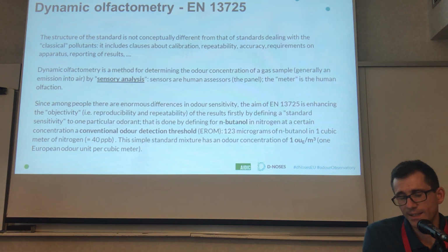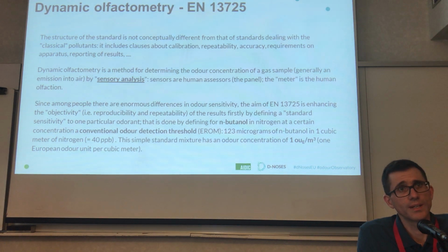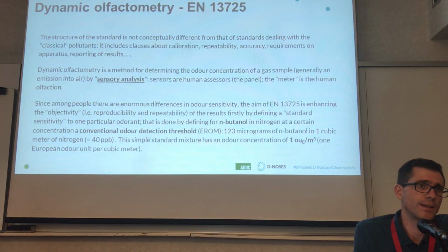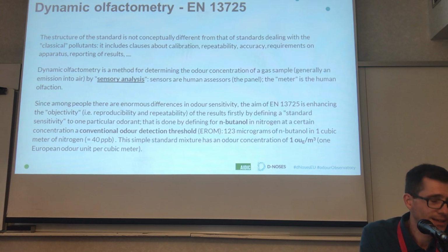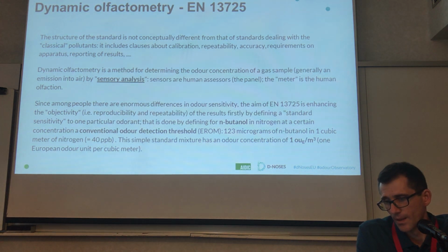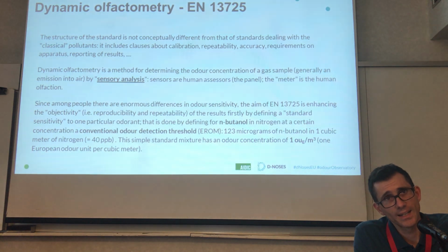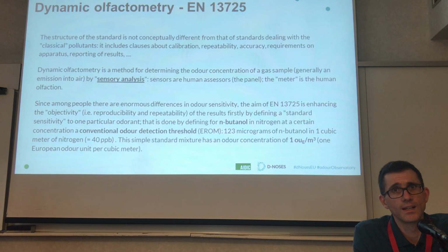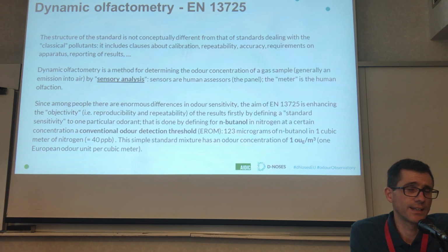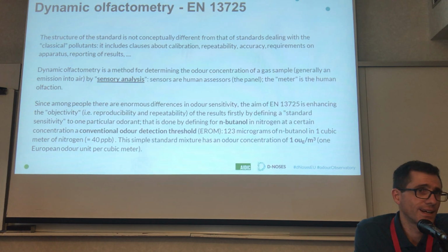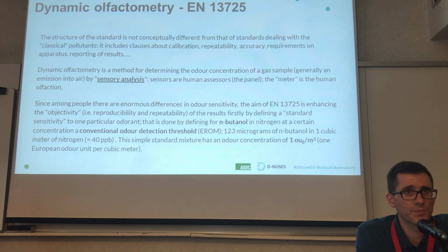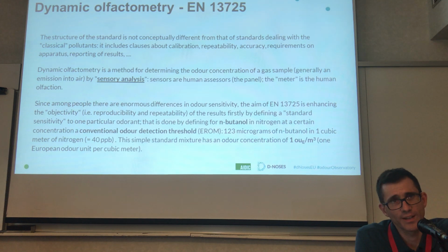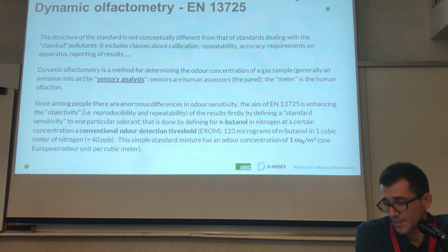So this solution has the result that a lab can buy a certified reference standard of N-butanol in nitrogen, so I can calibrate my measuring system by a certified reference material.